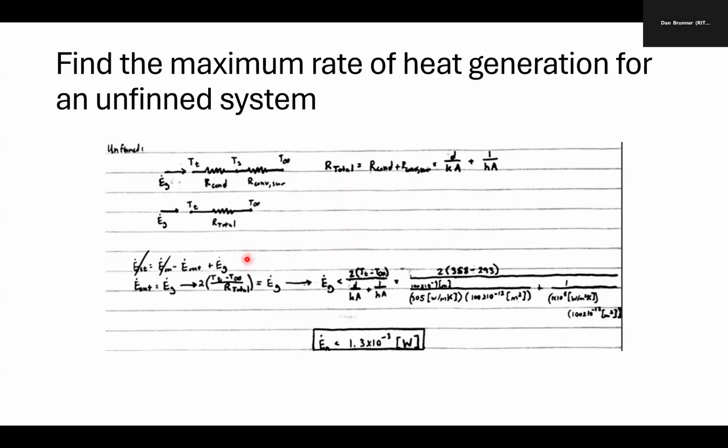Performing a closed system energy balance using the first law of thermodynamics, we can then say that the rate of heat generation is equal to the change in temperature across all resistors divided by that total resistance. And again, since we have the silicon carbide layer on both sides, we have to multiply this entire quantity by 2 because we have heat going through the top silicon carbide layer and through the bottom.